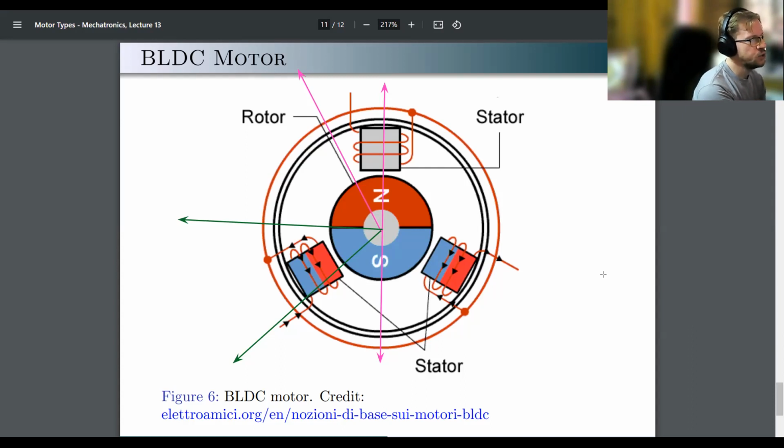Another option is to analyze back EMF. You remember from our model of DC motor, the back EMF term was present in the Kirchhoff equation. It's basically actual voltage that you can try to measure. They sometimes measure it, and based on back EMF of 3 coils, they'll be able to tell orientation of the permanent magnet inside your motor.